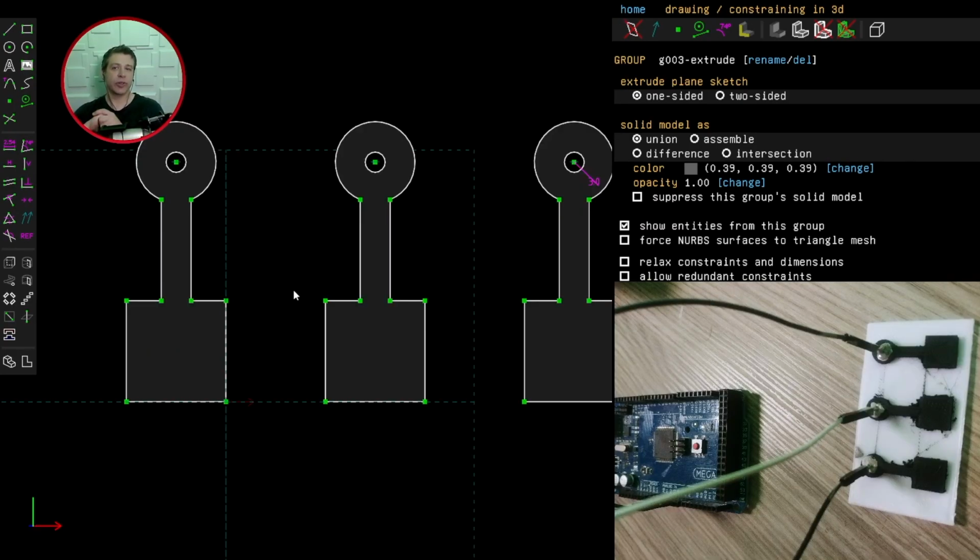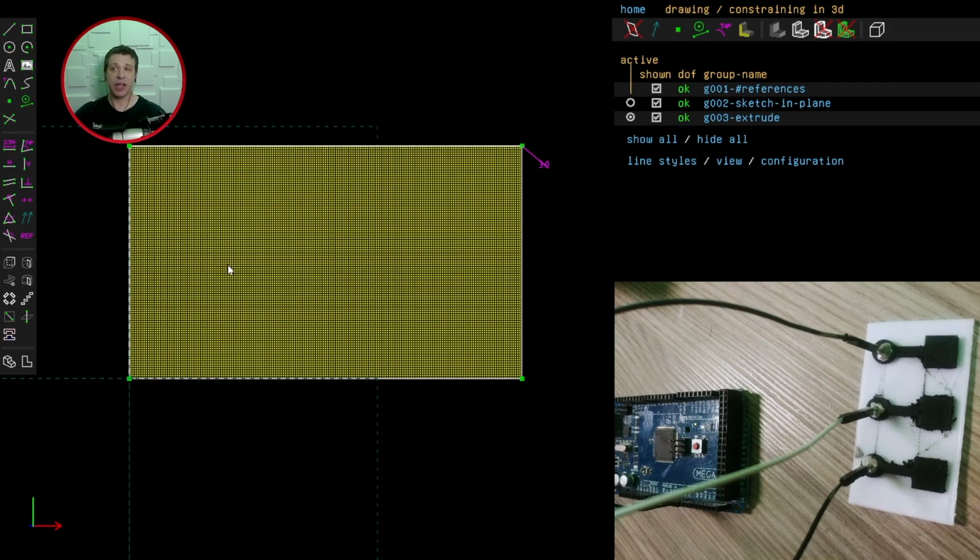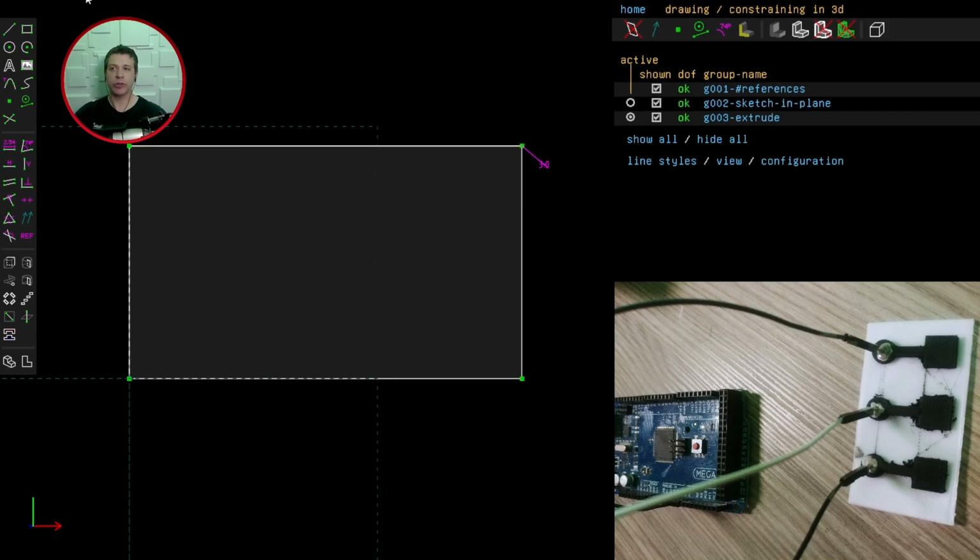The next thing I need to do now is to make sure that the keys have the correct global coordinates relative to the base, so that when we print it out, the keys will be on top of the base and in the correct position on the base as well. That'll become clearer now. Let's now bring in the keys. So I'll go to New Group this time. On the menu bar, go down to Link, Assemble, and I'll select the Piano Keys file, which I just created.